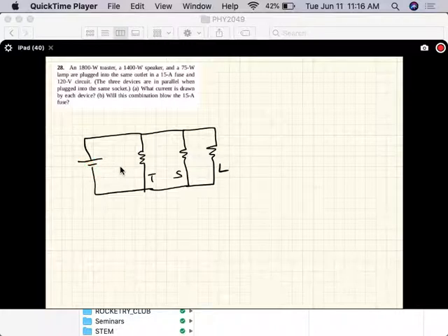And why do we choose parallel connection? Why do we connect everything in parallel? You see the same voltage, and if one device goes bad, all the rest can still function. This is how houses are connected to power lines as well. If one house burns down, that doesn't mean the rest of the world cannot live. So that's why we do parallel connection.